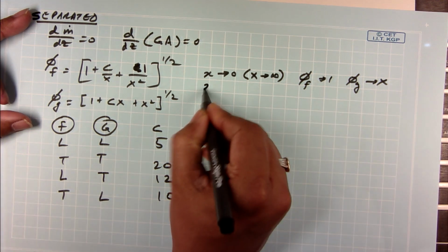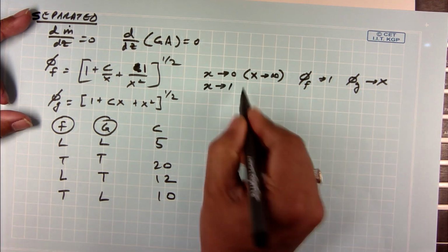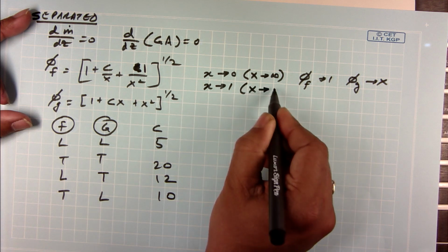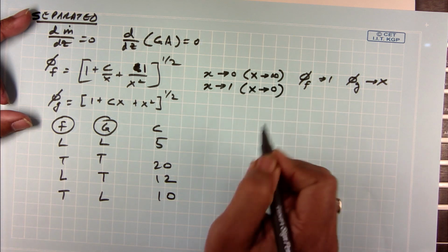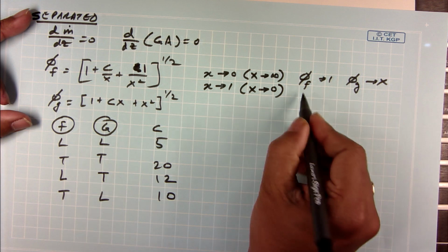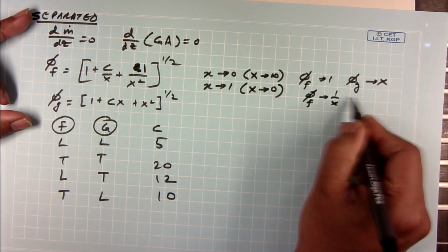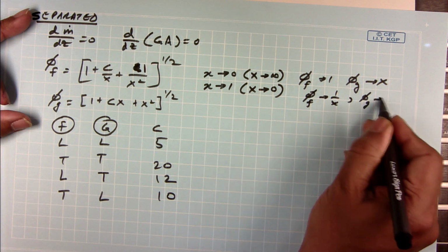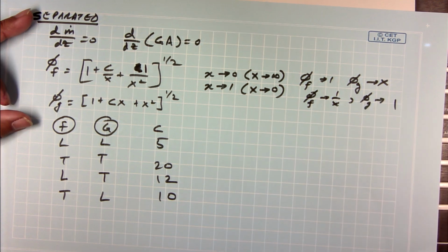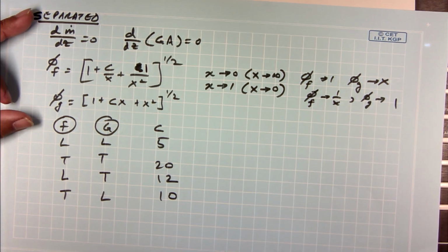And when you have pure vapor flow, that is x is approaching 1, your Martinelli parameter is approaching 0. Okay. In that case, your phi f approaches 1 by x and phi g approaches 1. Okay. That is the beauty of this particular correlation. It is very consistent with extension to pure liquid or pure gas flows.